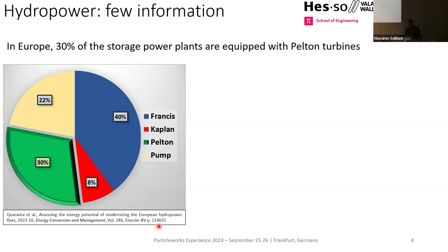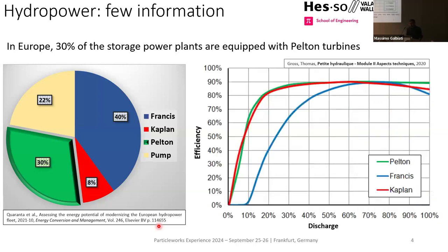And the main advantage of such a Pelton turbine is that if we look at the efficiency regarding the discharge range, we can have a high efficiency. So this is the green curve here. We can maintain more than 80% of efficiency for a discharge range from 20% of the nominal discharge to 100%. So if you compare to an engine, it is quite higher, obviously.